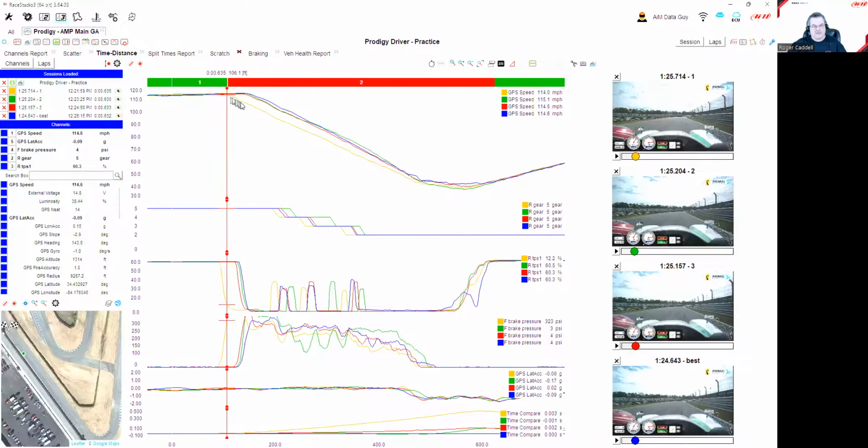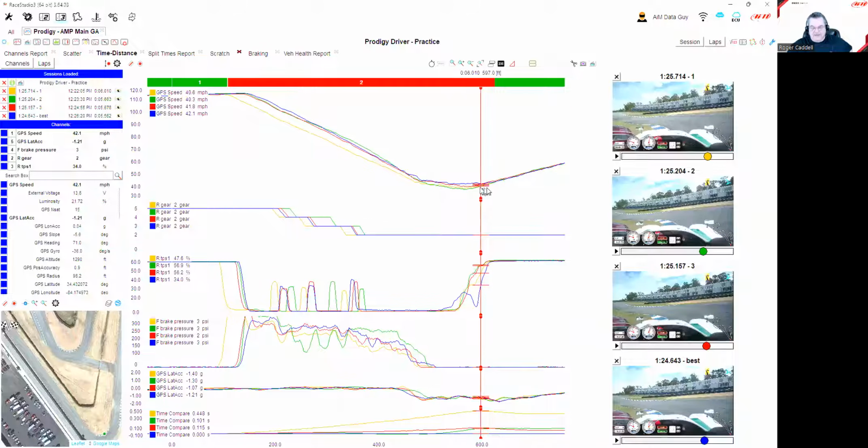You see how he got on the brakes early? And we're just looking at the speed trace. We could bring up brake pressure and look at it here as well. But he got off of it early and came down to meet the apex. That costs that driver, if we come up to here where the traces finally get back together, that orange lap lost 44 hundredths, almost a half a second, by coming in on the braking early, and your eye should have caught that really quickly in the time compare bar. All of a sudden there was a separation, right?